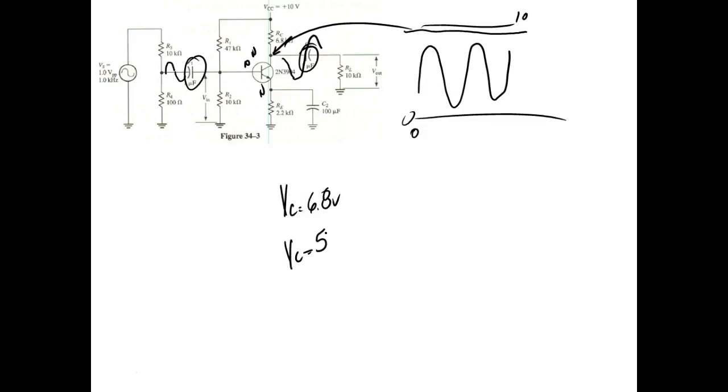But you're probably never going to see that because we're going to use standard resistors. Right? You understand that? Now, I was telling y'all we could bias this thing right in the center. I think Brian asked that question. Couldn't we do it if we put a bunch of resistors in series and stuff like that? And that's true. We could do it. But what you're doing is adding a lot of cost to something that you can get by with, right? As long as you know where it saturates and you know the maximum input signal you could put on this thing, you would never put more than that on there. And then what you do is you run it through multiple stages, right? You understand, to get the gains that you want.